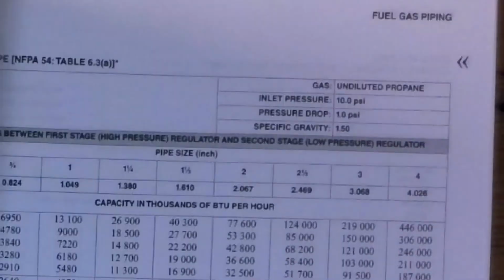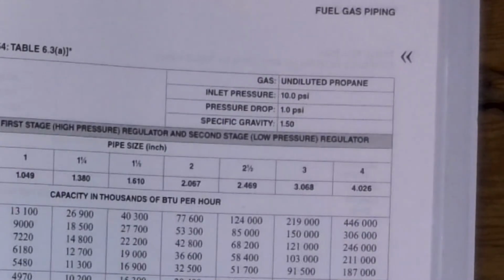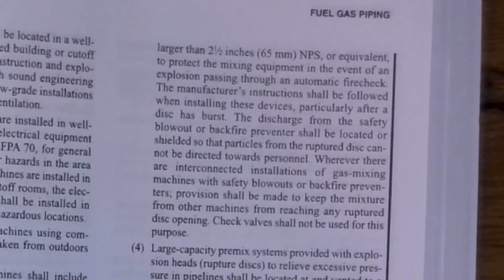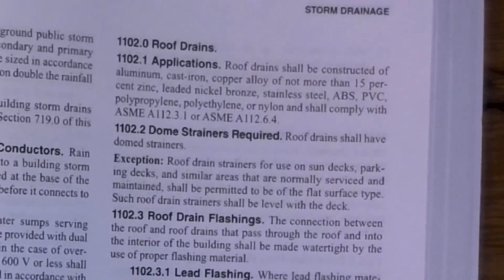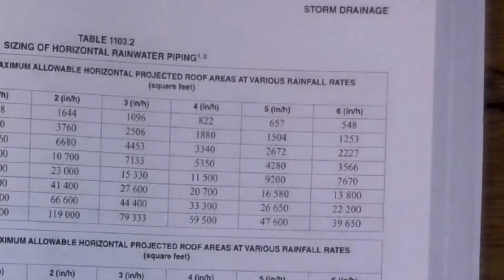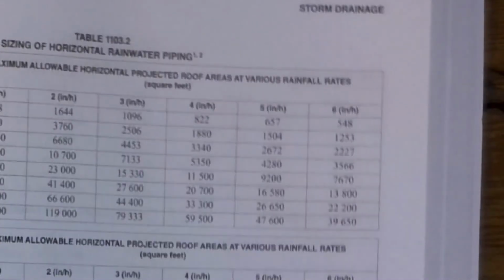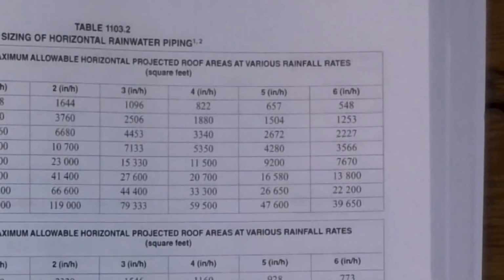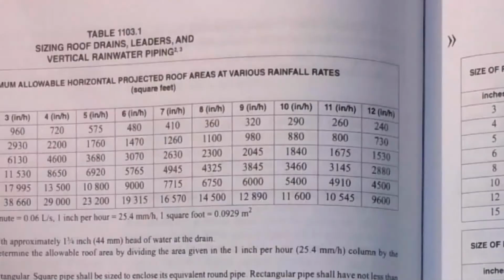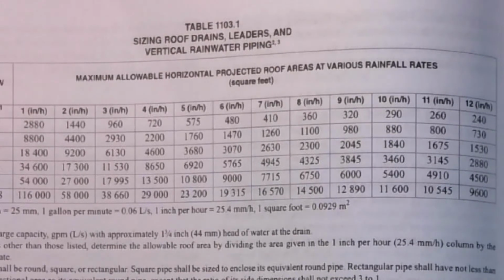What an authority having jurisdiction or an inspector will do in some cases is he will go ahead with approval if you do like a running water test. It's like, I can't get this thing on test. There's no way to do it. Just do a running test. So he's going to make you throw a bunch of water down the drain, and he's going to watch to make sure that it doesn't leak.